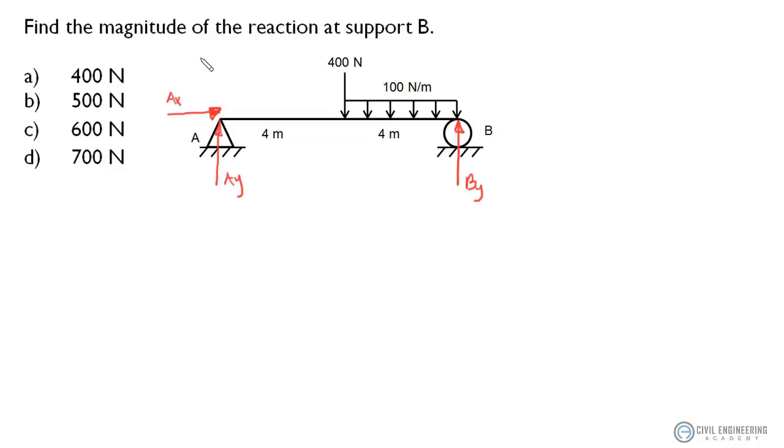But a quick way to see if a beam is statically determinate is to look at the number of reactions given the type of supports that the beam is sitting on. Remembering from statics that we have three equations essentially, we can sum the forces in the x direction and set those equal to 0.